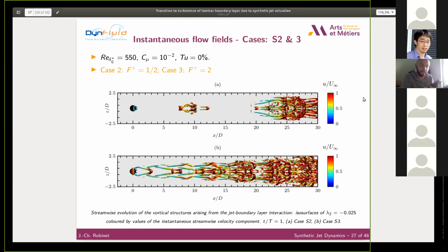Yeah, I never tried to do that, but it's interesting. The only case where we tried to compute a stability analysis is not for the jet, but for the roughness. It's work with Alessandro Bucci. I think he's here. Yes, he's here. In this case, we can compute the stability of the boundary layer. Generally in the near field, it's very intense. It's highly unstable. If we compute the convective instability with typically two-dimensional local instability tools, we have many especially unstable modes.